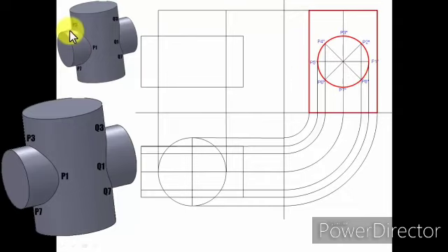that's it. Just like we had all the points in the form of P over to this side of this curve of penetration, similarly, you're going to have one more curve of penetration at the back also over here, in the form of Q. So behind P1 you're going to have Q1, behind P7 you have Q7, behind P3 you have Q3, and it's going to look something like this, right? Now these are all the points of penetration.